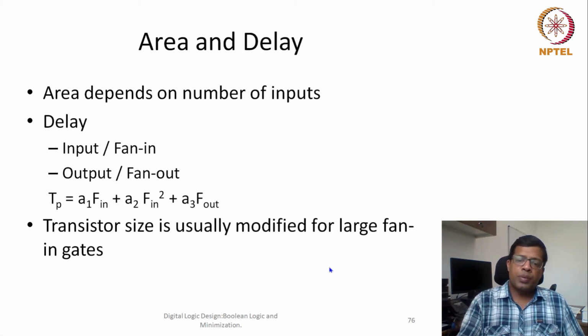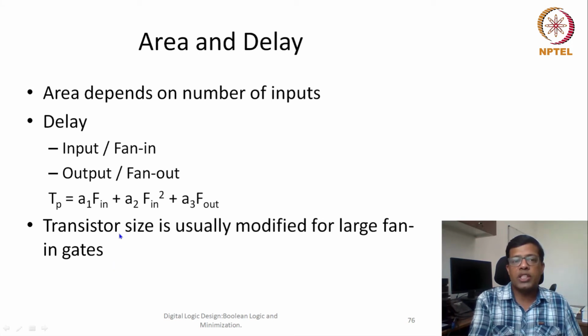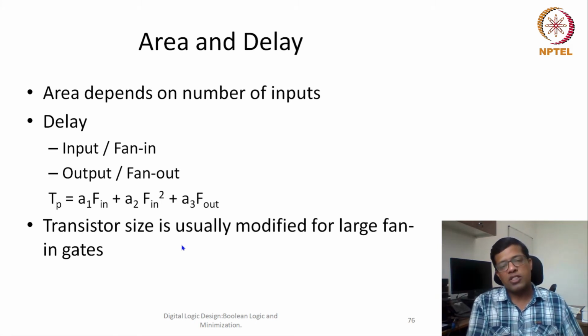And there is also an impact on area. The number of inputs would certainly increase the area, but because transistor sizing gets affected as the gate has a large fan-in, the size sometimes also increases, not linearly but super linearly, in the case of large fan-in gates.